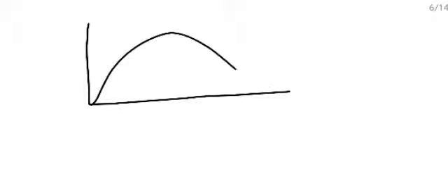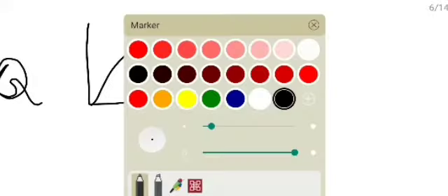So what I was telling, hydrograph only. When you are subtracting the W index, you will get whatever runoff there is. So multiplied by the area will give you the hydrograph. So this is runoff with respect to time.